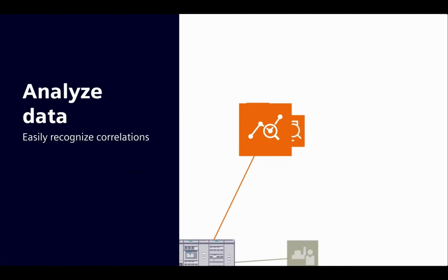To achieve this, the operational data of components like contactors and circuit breakers is analyzed. Temperatures are evaluated, and it also takes device-specific condition information. That means the behavior of the circuit breakers 3VA and 3WA is mainly affected by this blue block, which is visualized in the health mode.